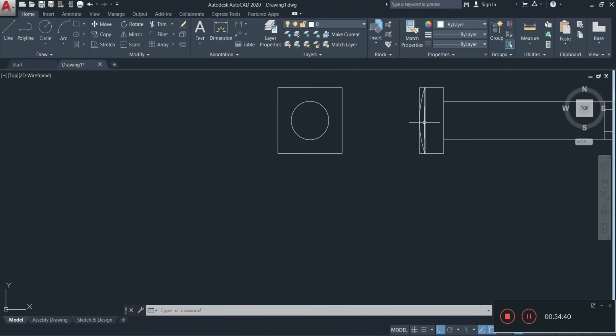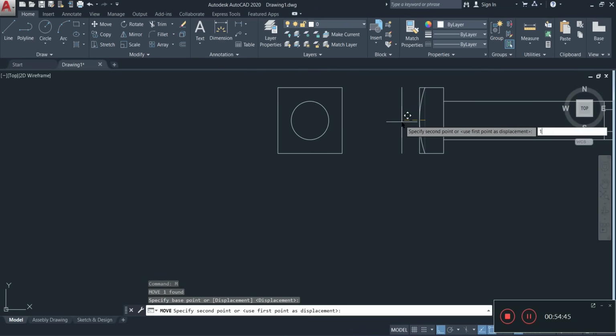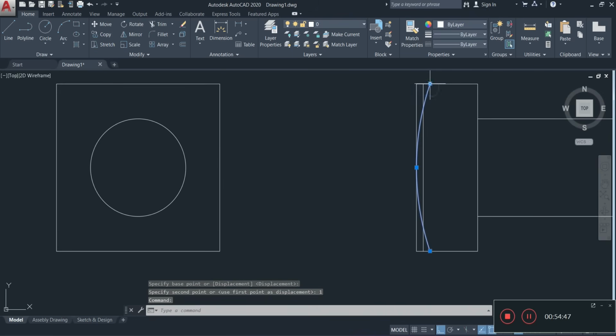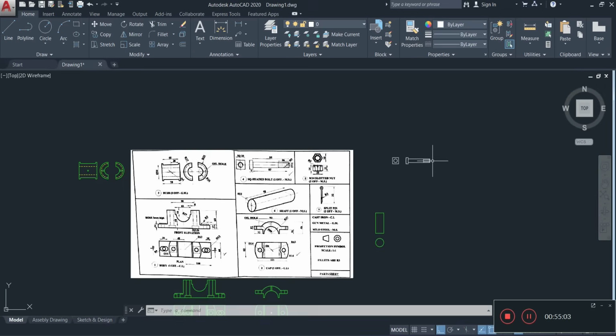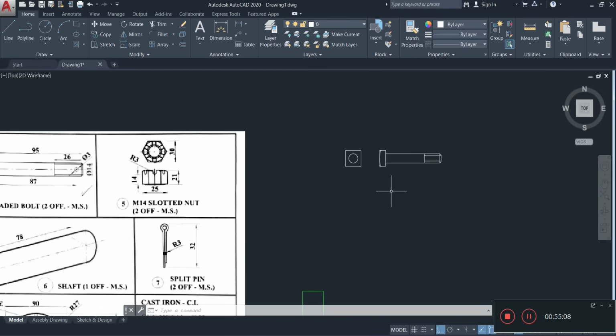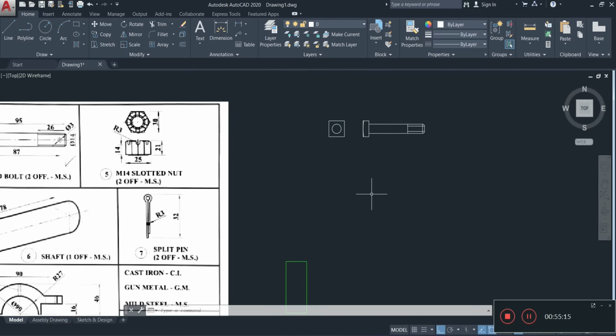Let me move this from the right to the left by 1, and I'll shift this now to that point. There's standards in relation to this now. It's because I think that you will not be able to measure these when it is printed on the paper. Alright, you have to simply use conventional notation to represent those. Alright, so once that is done, let's do the nut now, the slotted nut, or a little castle nut right there. Let's see if we can draw that one there.